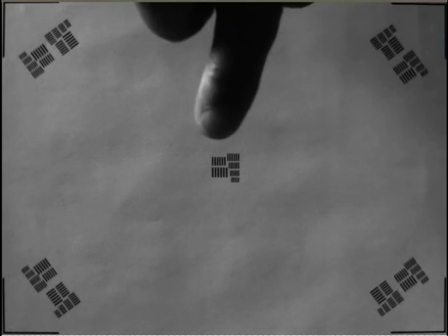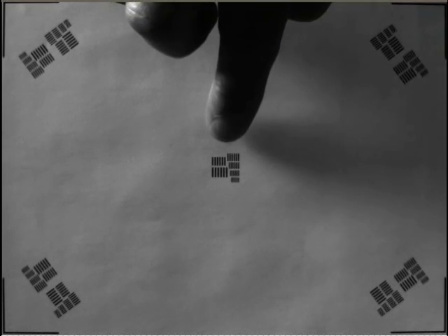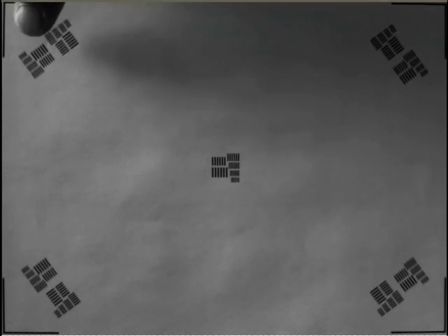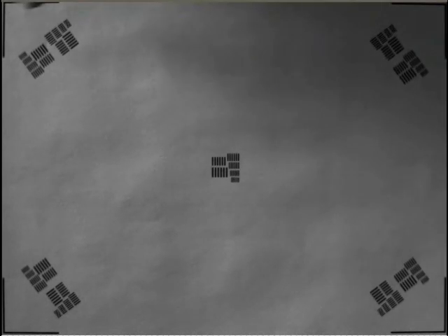And you need to measure this not only in the center, where the imaging resolution is typically the best, but out at the corners of the image, where, because of optical effects, image resolution can decrease. And you can do this either by making a pattern such as the one shown here that has the bar patterns replicated in the corner, or by moving your target around and moving the one bar pattern into the corners.